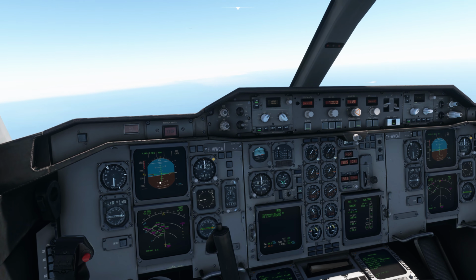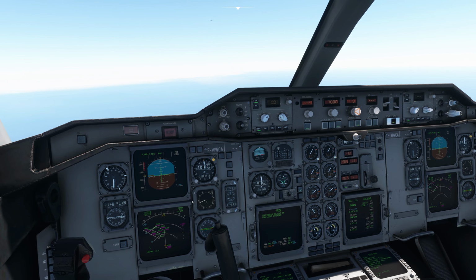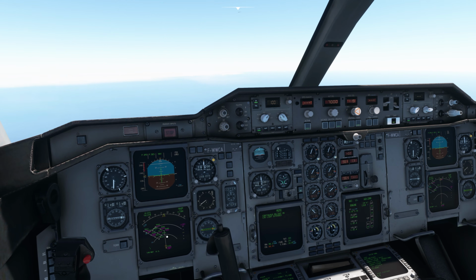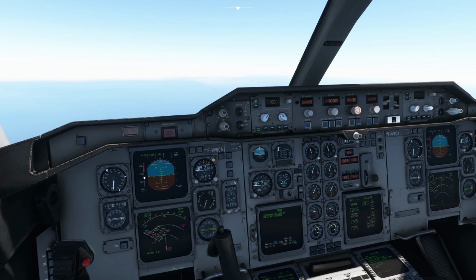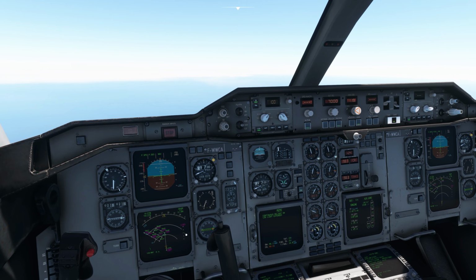Now with this I can extend the slats and I can activate profile mode, and now the plane will start to descend to 7,000 feet, and you will see this arrow coming which will indicate by which point I will be at 7,000 feet. So now the autopilot is automatically calculating it, and it will actually try to maintain such a vertical speed that my speed is not compromised. The speed remains 230 or as per the speed constraint, and it just descends.